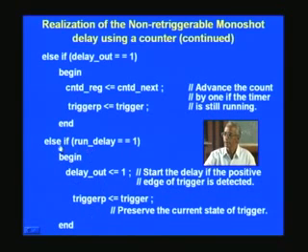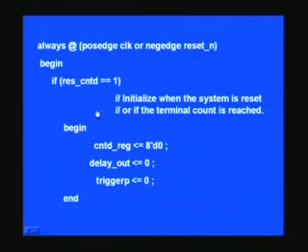So now this implies it is a priority encoder. Top priority is always put first, because naturally it is the reset which is very important, and we had to take a decision not to give priority to the advancing of the counter itself. And that's why this is a priority encoder. Wherever you have a priority encoder to be implemented, such as in bus arbitration in multiprocessor systems, you can use this way of coding.